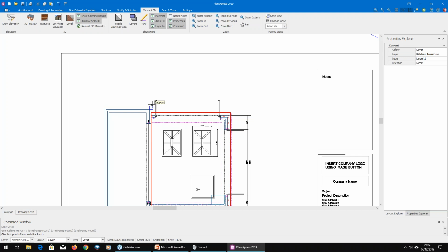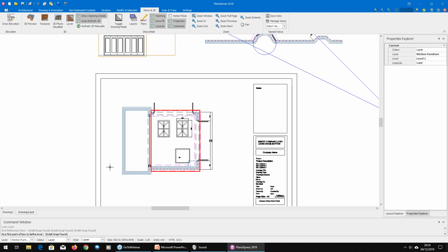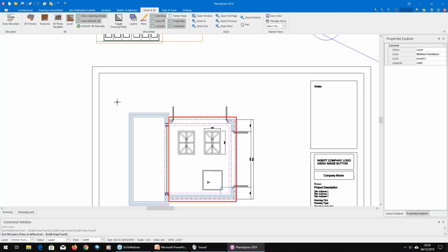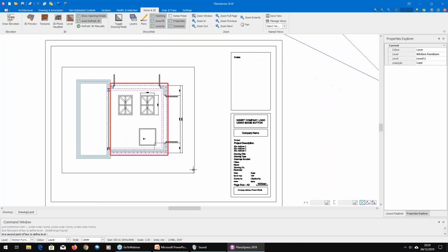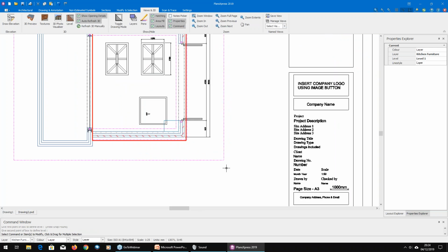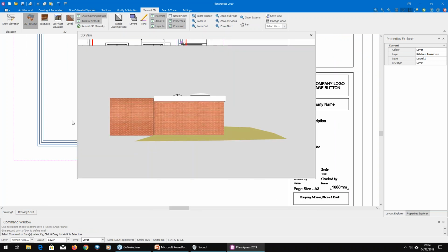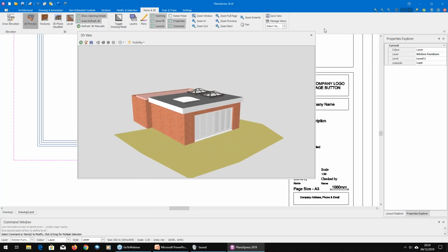Once I've clicked my reference point, it wants to know a box. So I'm going to click over here, off to the left and up a bit, clear of the drawing. Click once, bring my mouse down here and create a border clear of the drawing and place that there. It's important because when you do the 3D level, it'll only show things inside the level.